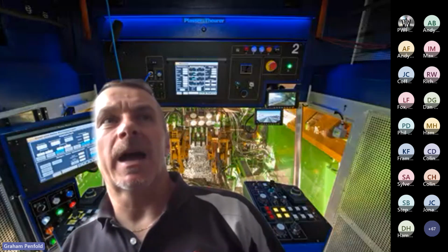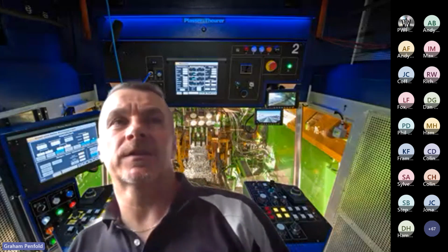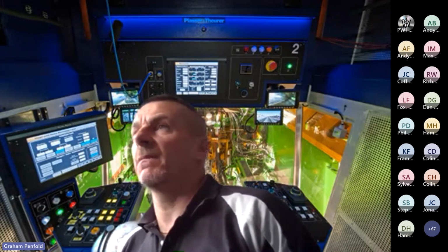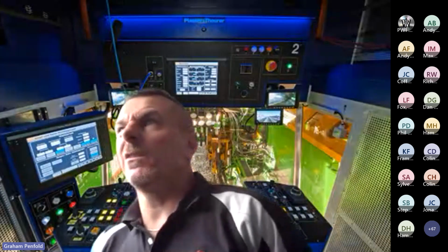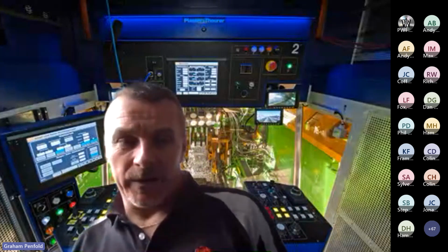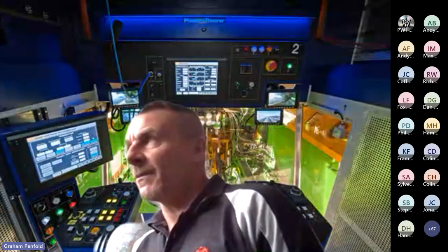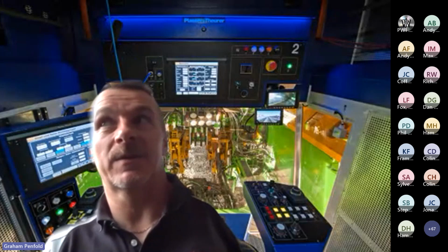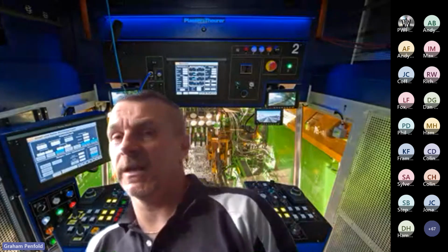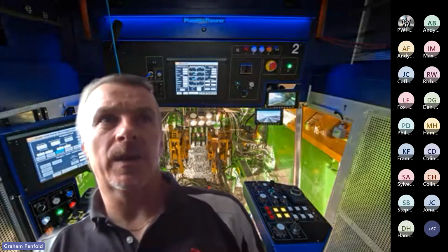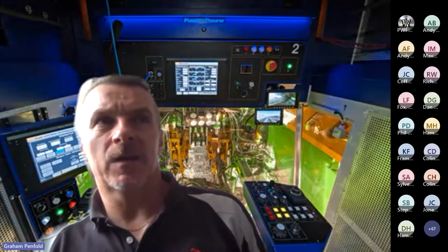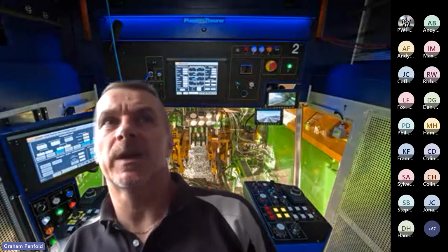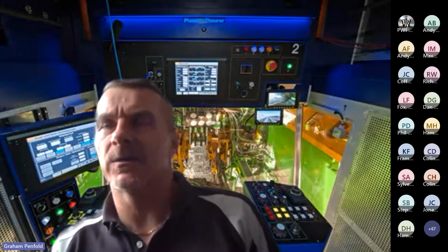The overlift you apply should be pertinent to what settlement you think, estimate, or calculate. So if we're going to calculate or estimate a settlement at, I don't know, 12, 15 mil, there is a bit of a point, because you probably get more longevity, but you've got to think about ballast levels as well. So the answer to that question is no. I wouldn't, because with current ballast levels, we have a massive problem with ballast as it is, particularly in the summer, and we don't really need to. If we stick to the realms of what we estimate settlement to be and go from there, we're getting the best of both worlds without compromising ballast and clearances. I wouldn't do overlifting higher than those values just for the sake of it.